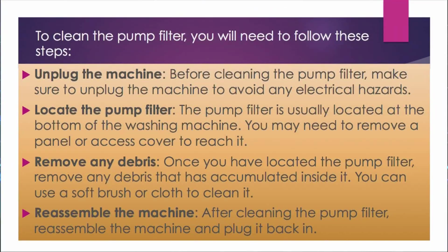So to clean the pump filter, you will need to follow some steps. First point, unplug the machine. Before cleaning the pump filter, make sure to unplug the machine to avoid any electrical hazards. Next point, locate where the pump filter is. The pump filter is usually located at the bottom of the washing machine. You may have to remove a panel or access cover to reach it.